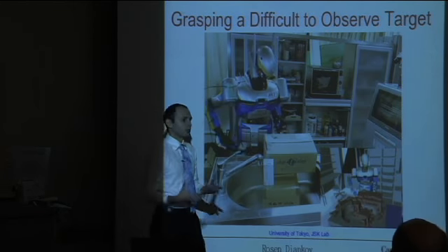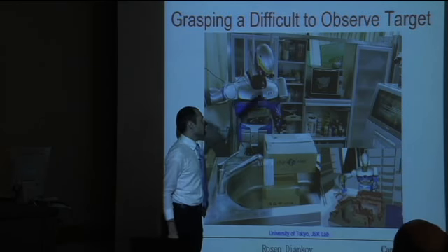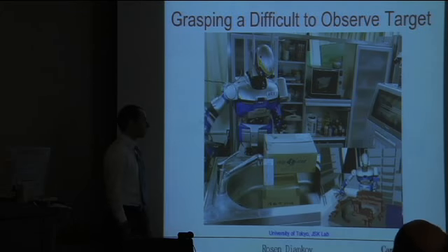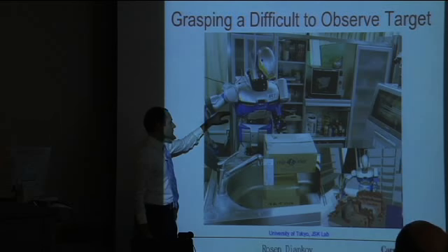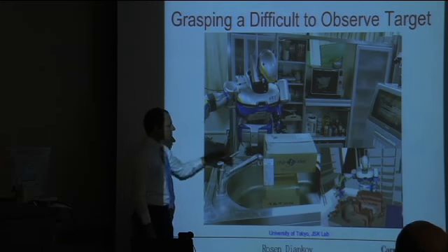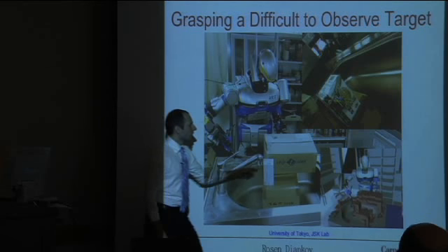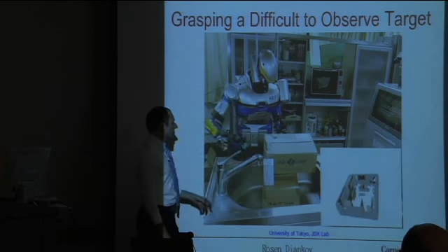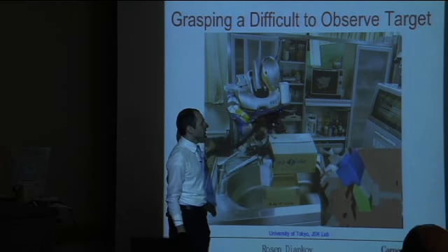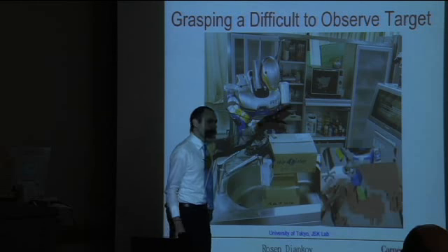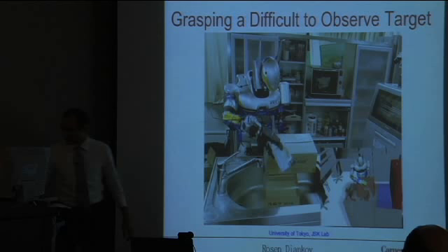Here is another more realistic scenario of a robot attempting to grasp this object here, where it's not viewable by the head cameras. We have initialized where the object is roughly in the system. And then the robot now uses its detectability extents to search for possible camera locations that can see the object roughly. It sees it here. And then it plans to grasp it. And note here that the boxes are really being estimated from range data coming from the laser rangefinder. And they're not in the original environment.